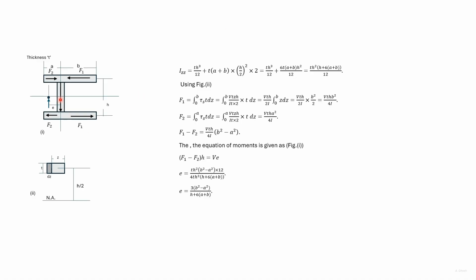Here we find the shear center for this section. This section is similar to an I-beam, except that the web is not in the center. If we apply a force passing through the shear center as shown, then the shear flow and the corresponding forces in the web and in the flange will be directed as shown. This we have earlier seen when discussing an I section.